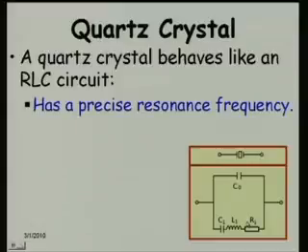Sir, what is C0? These are some capacitance values, C0, C1 are capacitance, L1 is an inductance, R1 is a resistance. Sir, this RLC is the bottom one. No, this entire thing is an RLC circuit. Okay, this is the equivalent of this. It's an RLC circuit. It will have its own resonance frequency, right. So, how to model this in this form, etc., let us not worry about it, but this is a model of this. Let us assume that there is a capacitance here across, and there is also capacitance, inductance, resistance involved here.